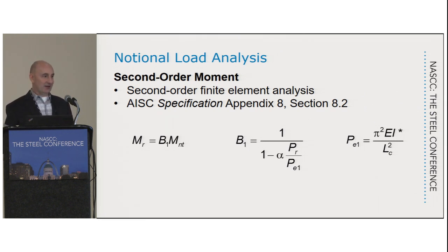And what I typically do for a finite element analysis, I do not typically add this to my giant finite element model with everything in it. Usually I'll just make a separate finite element model with one column in it, and I'll break that column. The first thing I'll do is put nodes at the ends, and then I'll break it up at the reinforcement ends, wherever the reinforcement ends at the theoretical cutoff point that we'll talk about in a minute. I'll put nodes there, and then I'll just break the rest of it into either 5 or 10 different segments and do a second order analysis on it. This is so much easier because the software I use will do all of these iterative calculations for you. It'll calculate the second order moment, and then it will design everything for you. So if you get everything in there right, you just press the button and you're done.